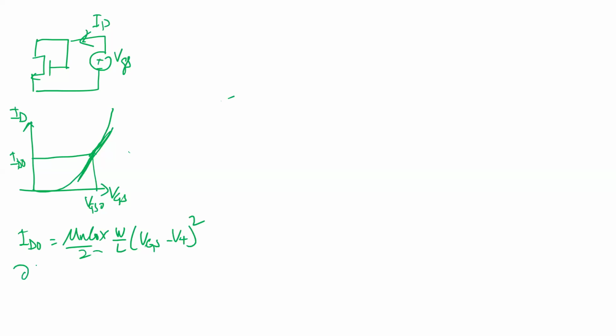It's a partial derivative because here there are three things which are varying, right? VGS, VDS, and the source to bulk. So you fix everything and vary one and find out what's the variation. Then you fix the other two, change one. So yesterday we just did two. We didn't do the third one because typically we don't use it. So we did the variation of ID versus VGS, and we did the variation of ID versus VDS, and that was your rout. Okay. So let's look at just the GM part of it.